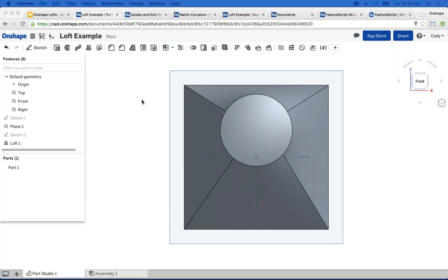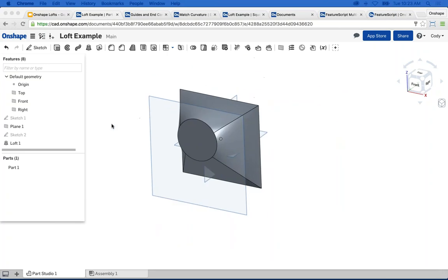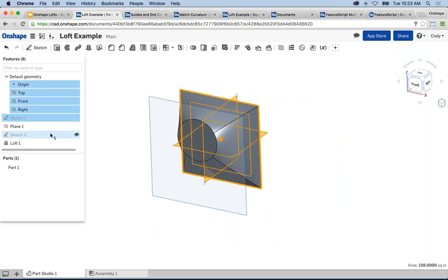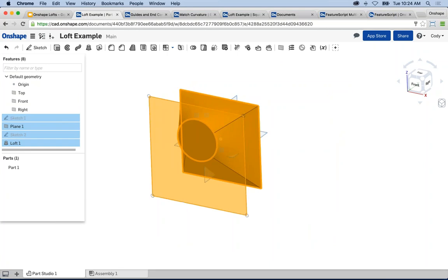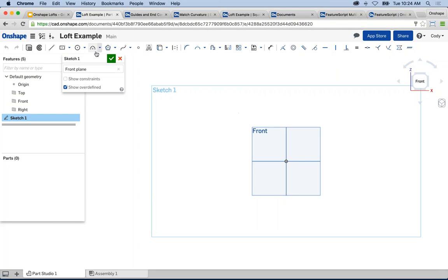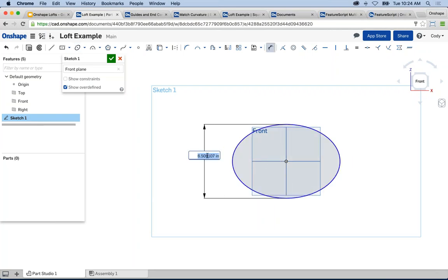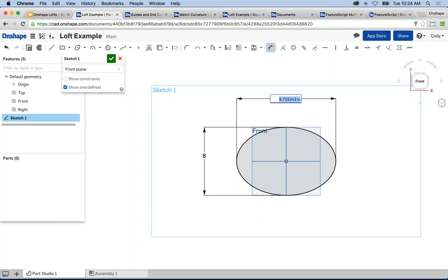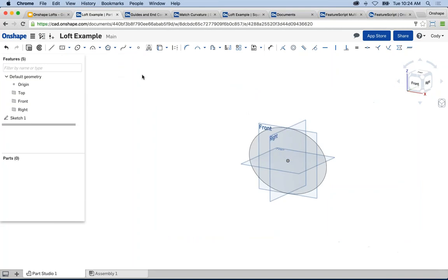All right, so I mentioned this a moment ago, and I do want to point this out. No nested contours. Nested contours is a limitation, and it's something I run into a lot with new users, so I do want to point it out. Just bear with me for a moment here. Let's create, again, something like a simple ellipse. I want a simple ellipse. Let's give it a few dimensions, say 6 and 8. So I've got this basic ellipse shape, right?